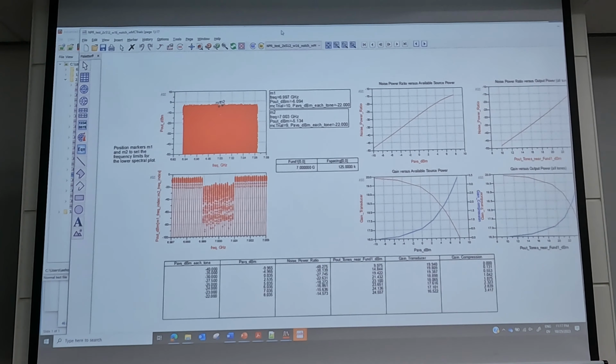It's easy to just say, okay, I'm going to turn off a channel and then, in a spectrum analyzer, measure what appears in that channel at the output, that's the distortion due to all the terms mixing into it. I think it's a tradition from measurement, but I think probably error vector magnitude is the more accurate way, or a better specification, but NPR is still around because of tradition, maybe. But I'm not an expert on it. Thank you. Cool.